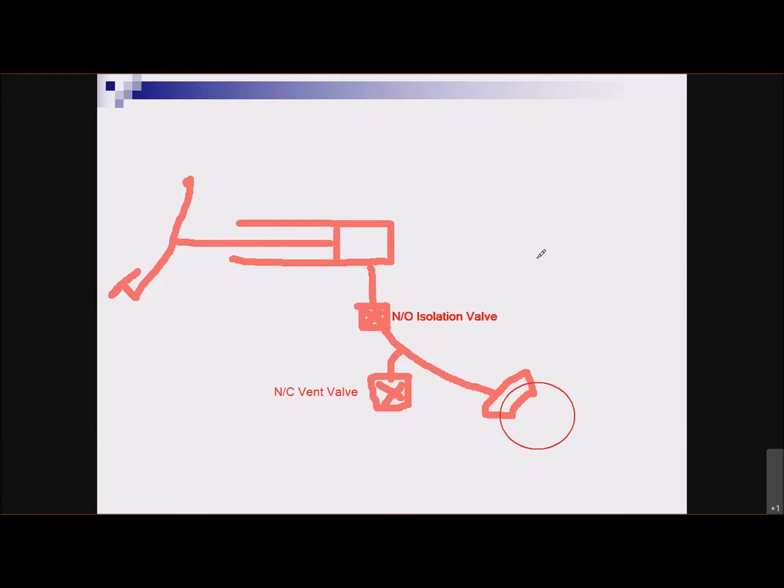And that may be all that's necessary, right? So it energizes that solenoid, it closes. Now, all of a sudden, what that does is it blocks any further pressure from your foot from making it to the caliper.